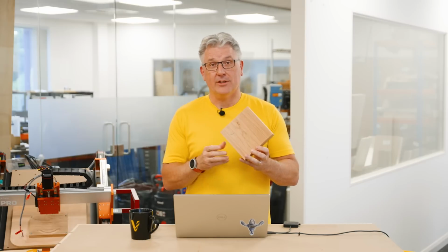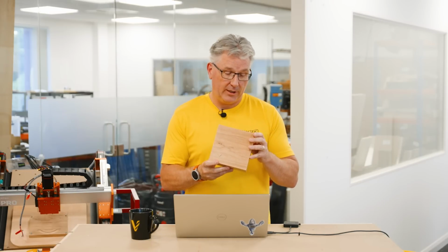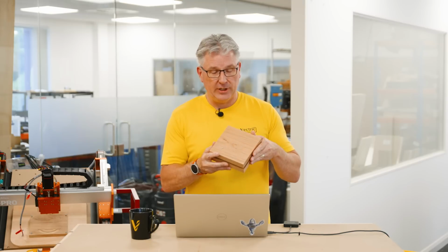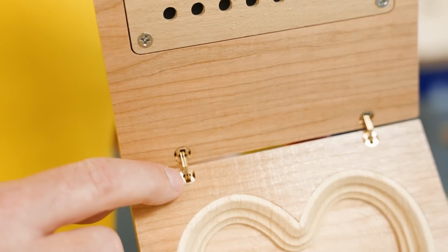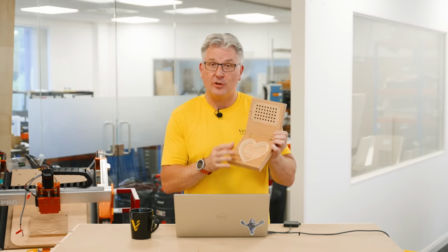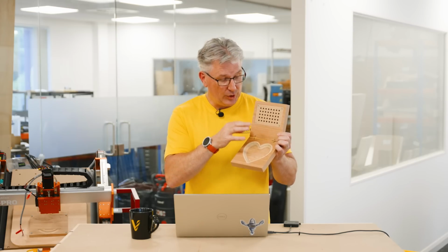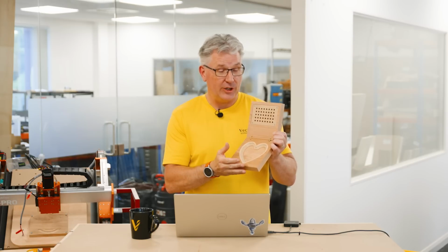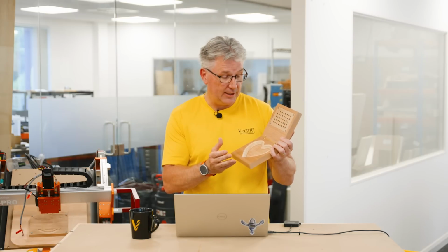I'm really happy with the way that turned out. All the parts worked together really well. My top tips for this one would be to make sure that you measure the holes for your hidden hinges. If you're going to use that, it's really important that they're the right depth and everything. And when you go to assemble it, make sure the hinges are pointing pretty much straight on, or you're going to end up having an issue with that.